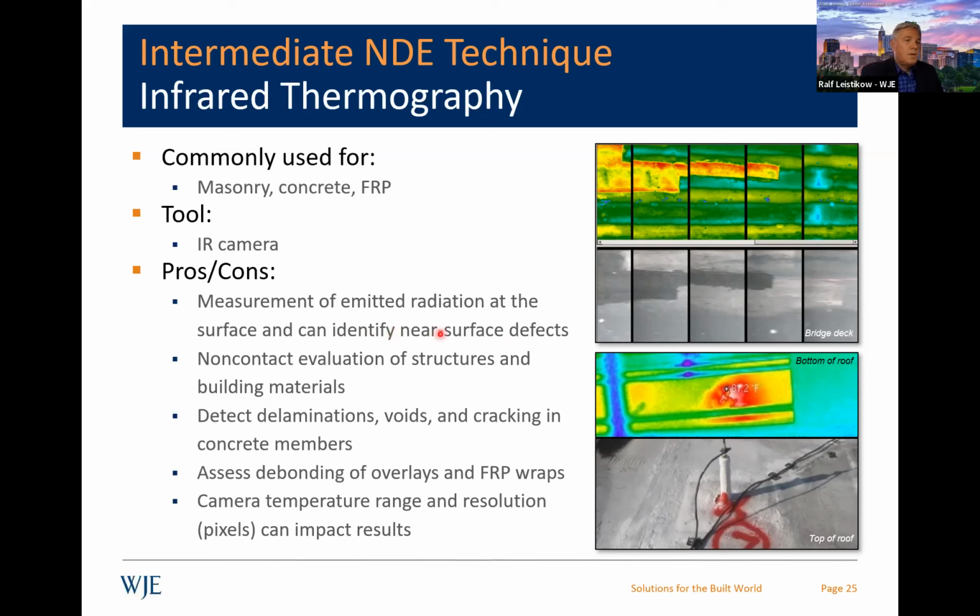And sometimes we're seeing people reading more into it, where you're actually looking at moisture in walls and you're looking at the surface, and it may be heating from just the sun or reflections off of adjacent windows and things. So there is some training or knowledge required to use these. They do give you great information, but you've got to be careful. You are reading the surface. You're not reading anything really behind it. So if you have a stud wall and gypsum, that may not be indicative of the wood framing.